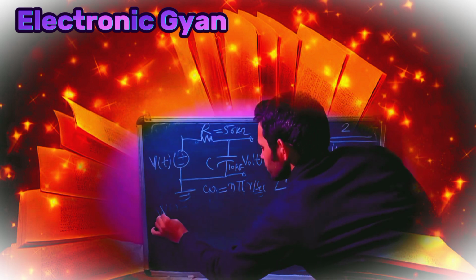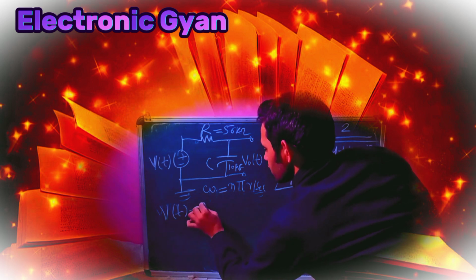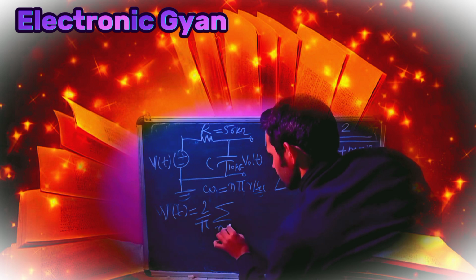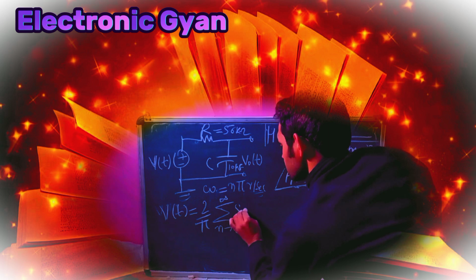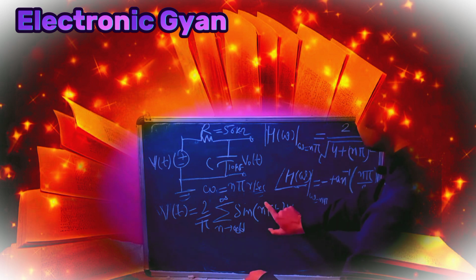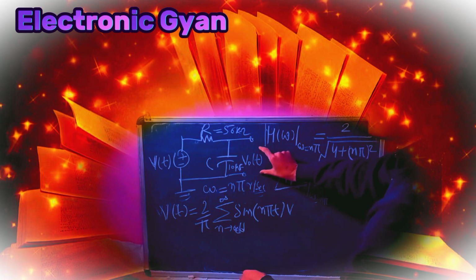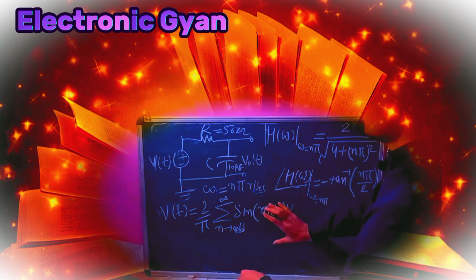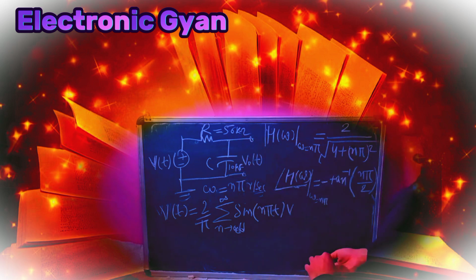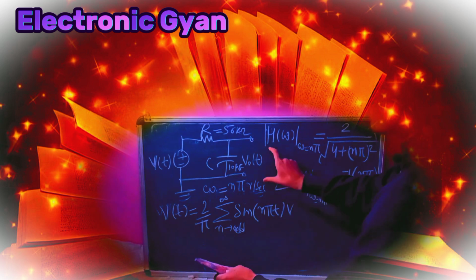Where my input was what? V(t) is equal to 2 by pi, that we have obtained, summation n odd to infinity sine n pi t volt. So at the input frequency we have found this. As we know very well, the steady state output voltage for a given sinusoidal input voltage passing through an RC low pass filter, which is an LTI system, is obtained as follows. Let's see what will be the final output.